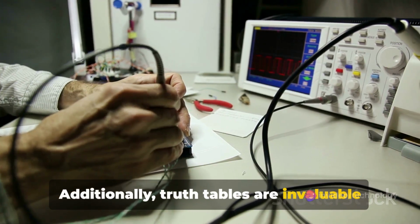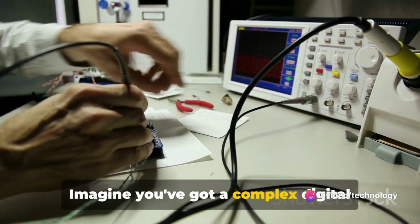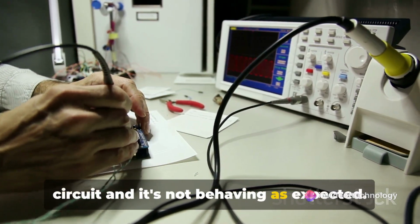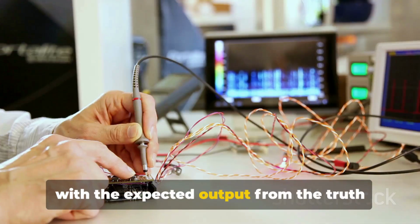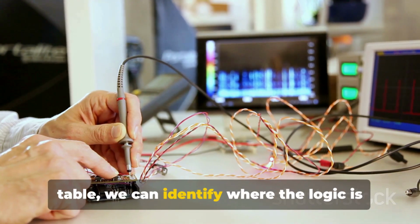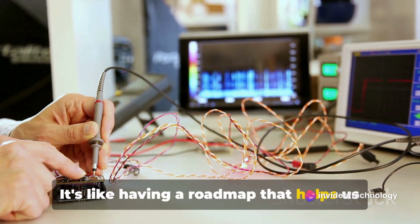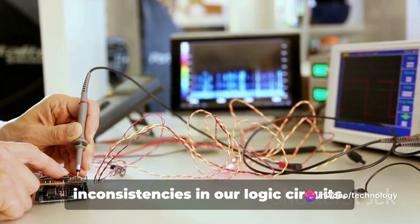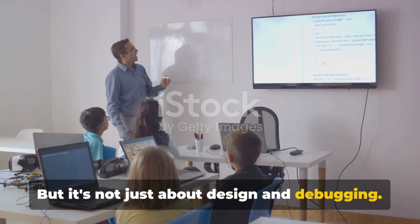Additionally, truth tables are invaluable in debugging digital systems. Imagine you've got a complex digital circuit and it's not behaving as expected. By comparing the output of the circuit with the expected output from the truth table, we can identify where the logic is going wrong. It's like having a roadmap that helps us troubleshoot and rectify any inconsistencies in our logic circuits. But it's not just about design and debugging.